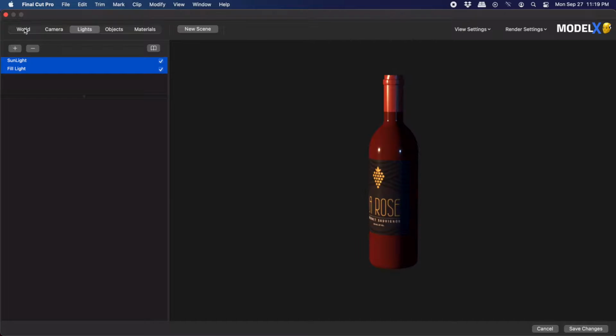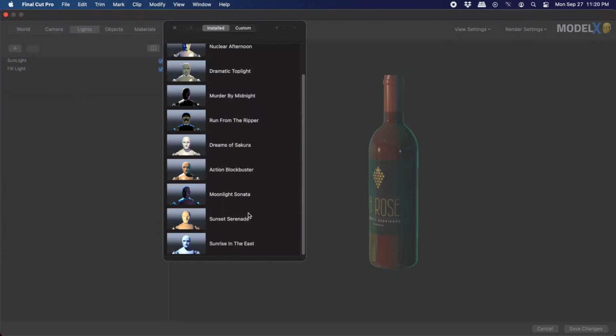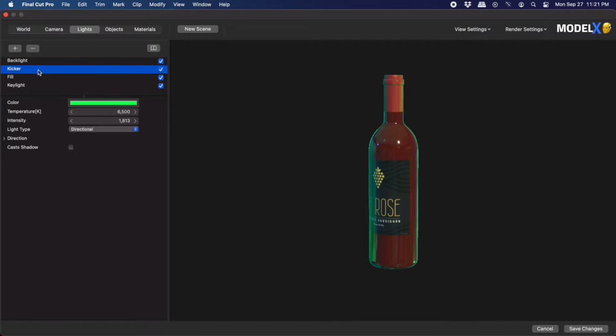For some additional fill light and realistic accents, go to the World tab and turn up Environment Lighting Exposure a little bit. The lighting workflow will involve finding a solid balance of world and specific lighting to get your result. Don't be afraid to be brave and experiment with pushing the color and saturation and brightness for specific graphic effects.